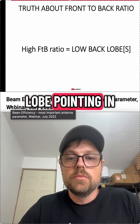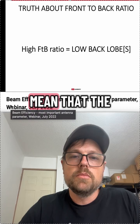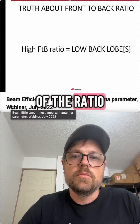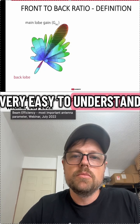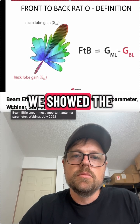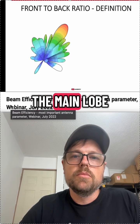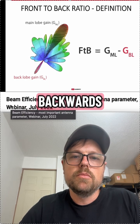This is the lobe pointing in the opposite direction as the main lobe. It can also mean that the group of side lobes around the back lobe is small, depending on the definition or the way the front-to-back ratio was determined. The front-to-back ratio is very easy to understand. Looking at the radiation pattern of an antenna, in this example we show the pattern of a directional patch array. The front-to-back ratio is the difference between the gain of the main lobe and the gain of the back lobe, which is pointing backwards.